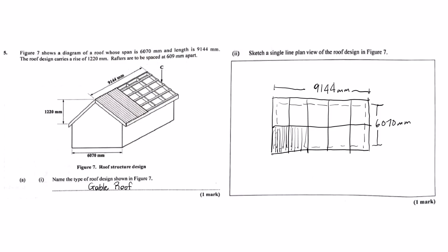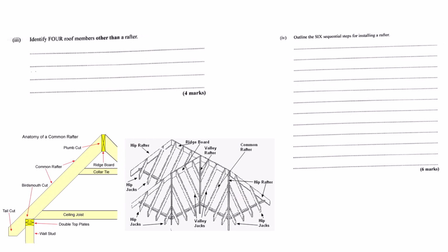Okay, first you've got the ridge board. It's a horizontal beam running right along the very peak, the ridge. It's where the tops of the rafters meet. Think of it like a central spine. It helps keep all the rafters lined up properly, alignment, and gives them a solid surface to fix to at the top. So kind of like the keystone in an arch, helping lock it together? That's actually a pretty good analogy. It helps distribute the load, too.